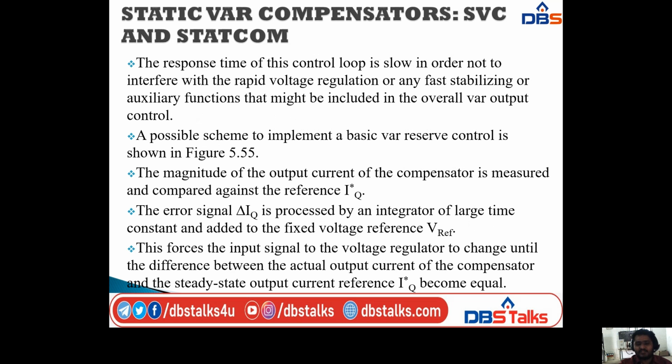Next, this delta IQ and V reference value forces the input signal to the voltage regulator to change until the difference between the actual output current of the compensator and the steady state output current reference, that is IQ conjugate, becomes equal.